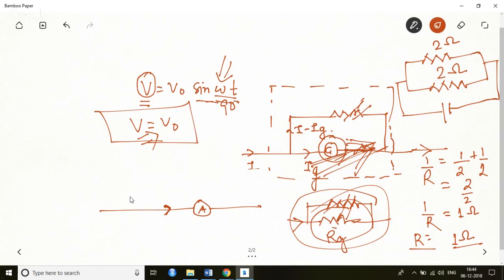Why do two things again? Two, three things in common which I want here: how do I measure voltage? By putting things in parallel. So I put things in parallel. How? I will put the galvanometer in parallel to the points where I need to measure the voltage. But the galvanometer will have certain resistance. I don't want small resistance here. I would like to increase the resistance so that very small current is wasted due to connection of this galvanometer. That is why, with the resistance of this galvanometer, I will put a resistance in series.